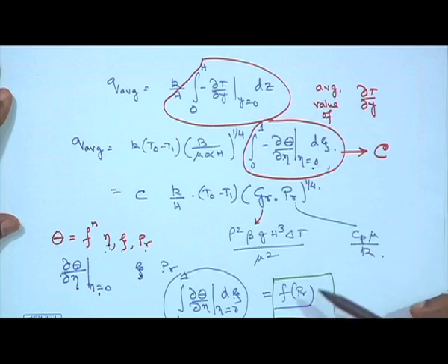and we also know that even though it is a function of Prandtl number, it must be a slow or a weak function of Prandtl number, because we have earlier said, since the flow rate is slow in convective heat transfer, at the limiting case it approaches the creeping flow, but this is not a case of creeping flow. We have still very slow flow. Since it is very slow flow, the dependence of the solution on the values of the Prandtl number will be very small.